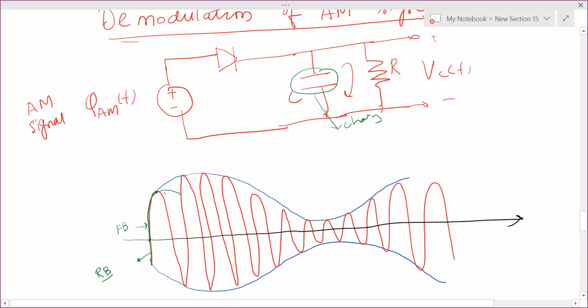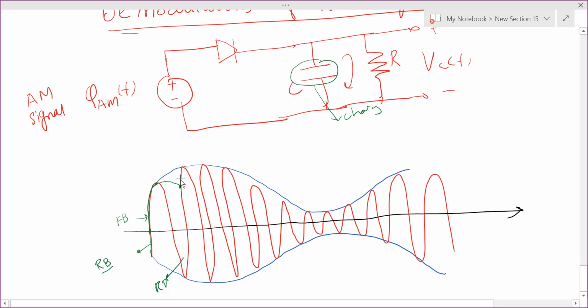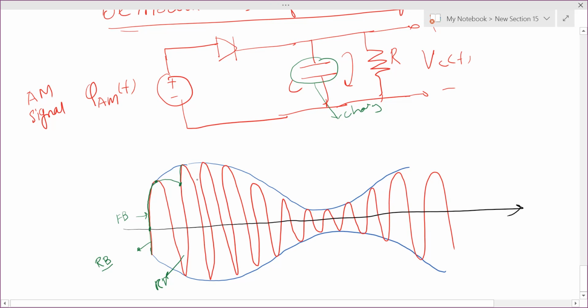Now at this point the signal value has risen again. In between, the diode will be in reverse bias again, but during that time the capacitor will discharge. Then again the capacitor will charge, it will elevate. Now again after this point the capacitor will discharge, but slowly like this. So reverse bias, again discharge, again discharge.